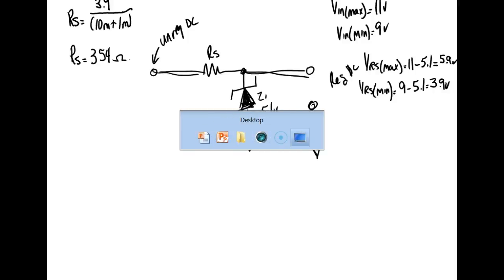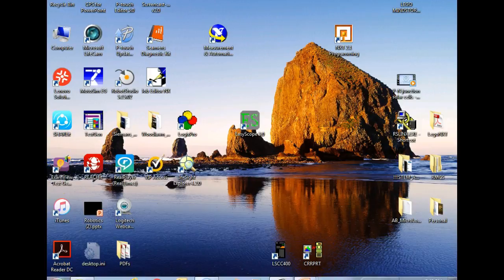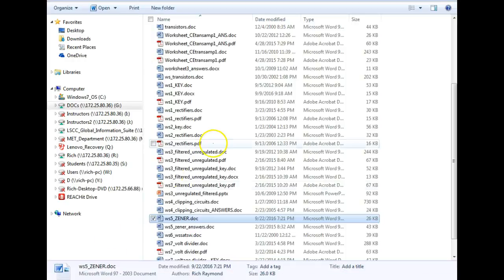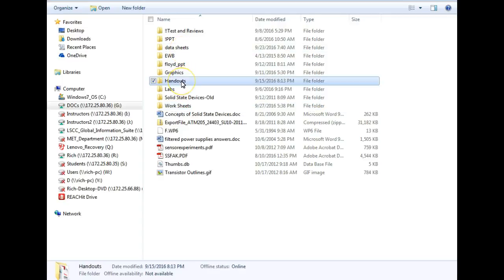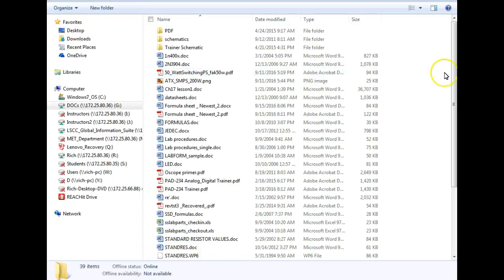So you had to use the internet for this thing, right? I'll print that off. So what we'll do is we'll look at the standard resistor chart and figure out which one we're going to use. And what are we always going to do with this guy? Always. Which way? We're always going to round down.